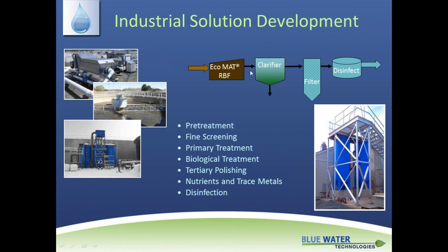So as I mentioned, a lot of our projects we're just chasing after compliance for trace elements. But a lot of times when you're targeting a specific element, say zinc, zinc is an element that likes a higher pH for absorption. You'll get some precipitation of dissolved solids if you're in an application that has very high TDS. So it's often necessary to have a clarification, a precipitation stage up front, followed by our Blue Pro system. And again, this is really the key for compliance throughout our conversations and process design. So I'm going to be spending a lot of time defining that unit process as we go on here.